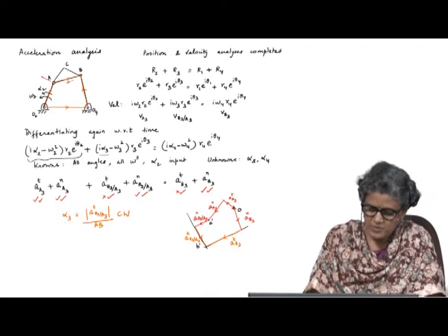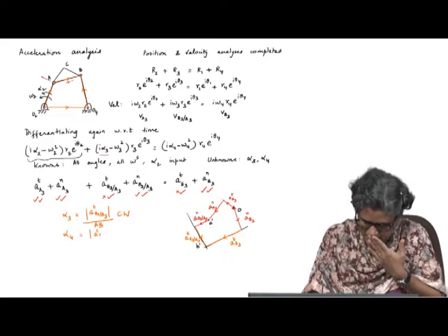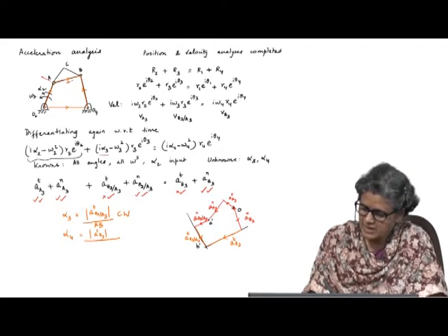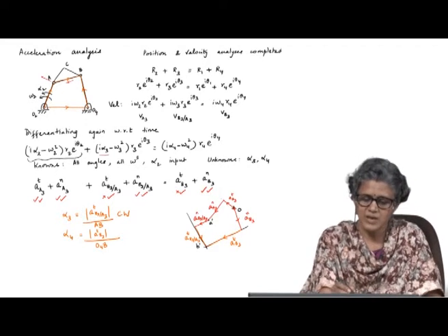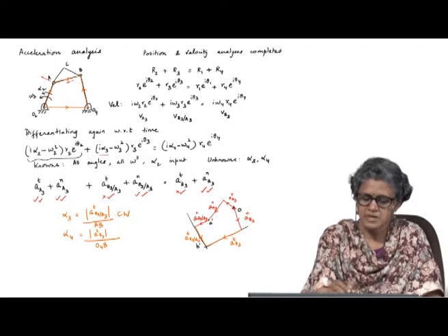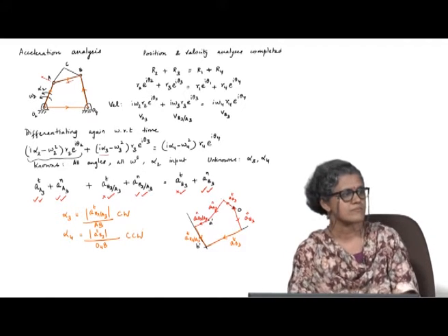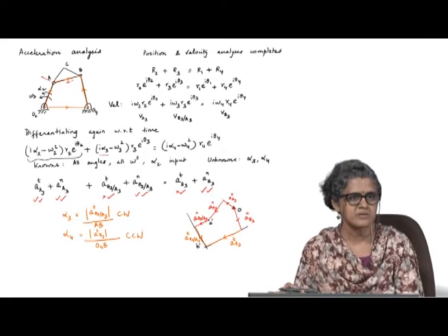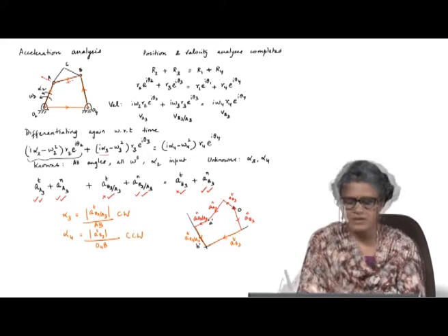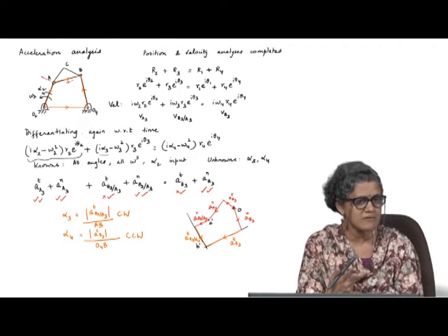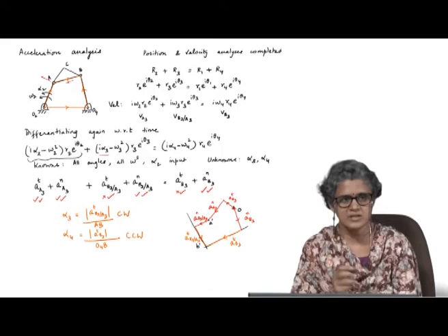Okay. What about alpha 4? Alpha 4 is A tangential B3, magnitude of that by O4B, and what is the direction of that? So, you have the direction perpendicular to OB like this, which means alpha is counterclockwise. This should be familiar to you. So, this is how you solve it; analytically you will just split it into real and imaginary parts. You will have two linear equations in alpha 3 and alpha 4, and you would solve for those unknowns. Graphically you would solve it in this manner.